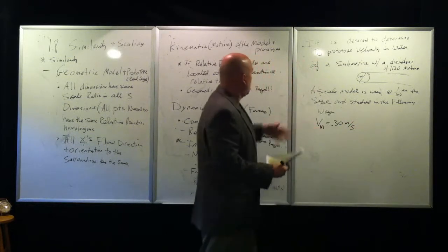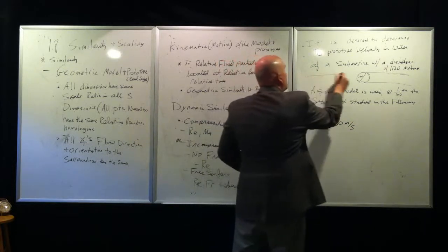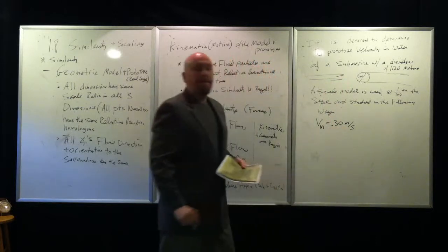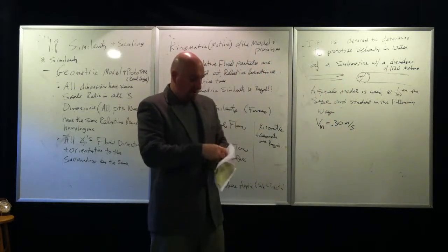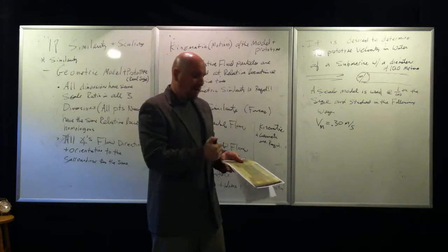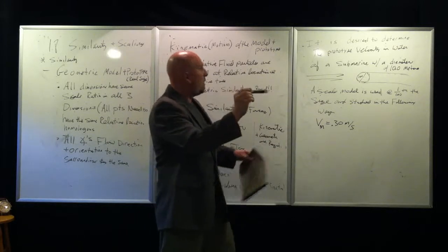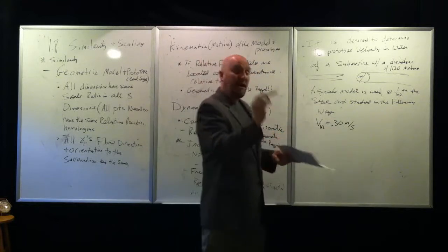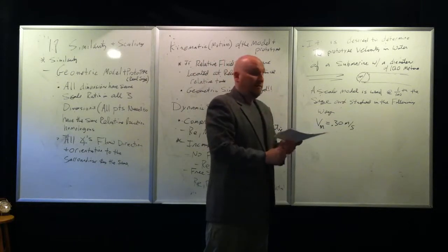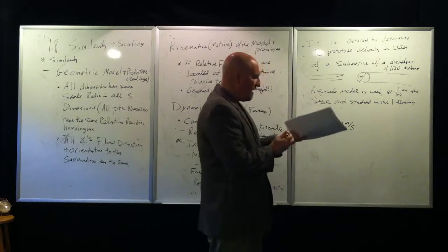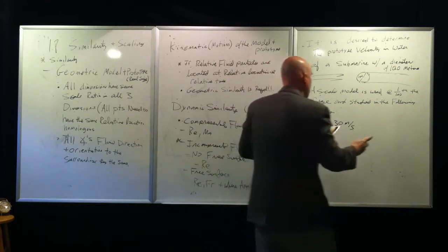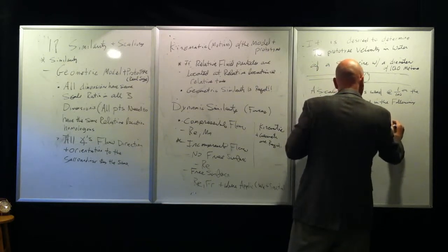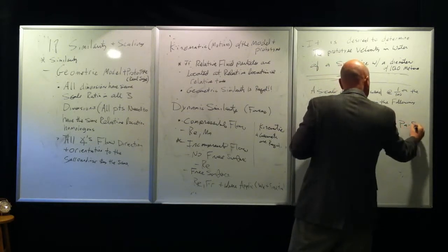The velocity of the stream going over the model is going to be 0.3 meters per second. So put this marker in a chamber and run water over it or past it at 0.3 meters per second. That's going to be the velocity that the model is going to be running at. And let's say the fluid properties for the model, the viscosity is going to be 1.5 Pa seconds.